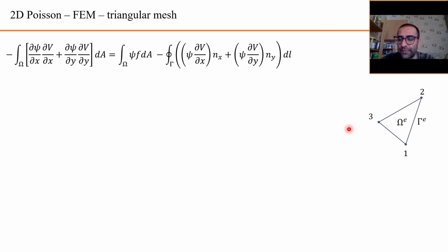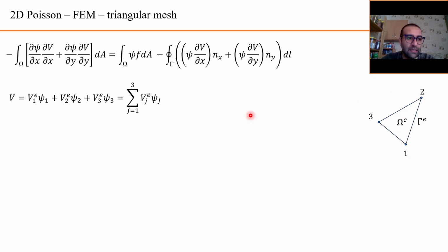We know that we should solve this using the finite element method. For each element, we have some number of nodes. Using linear shape functions, we have 3 nodes for any triangular element. Therefore, we need to solve such an equation for all the nodes, and we need to define some shape function at each node.